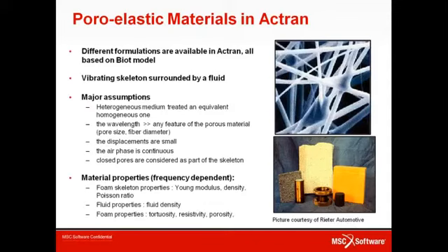The model developed by Biot relies on the knowledge of several material properties. First, there are the mechanical properties, for instance, the Young modulus, or the solid density, or the Poisson ratio of the skeleton. Then there are the fluid properties, mainly these are the fluid density and the sound speed. And then finally, we have the properties of the foam, the so-called Biot properties, and those are the tortuosity, the flow resistivity, and the porosity. And the meaning of those properties will be explained in the next slides.